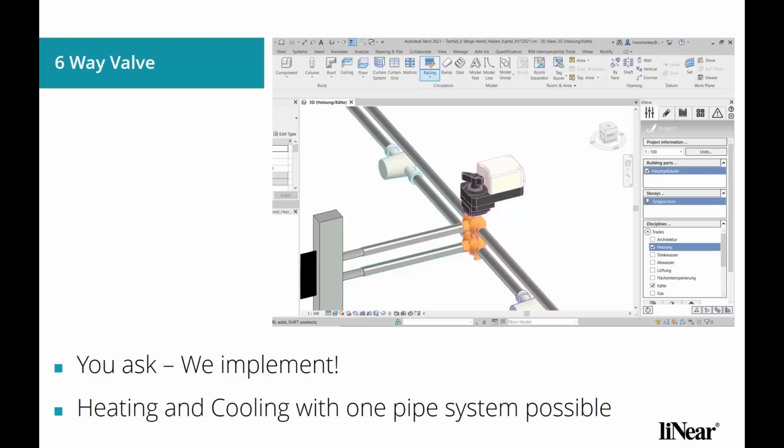With the liNear Analyze modules, this component can also be calculated within the pipe network calculation. With these valves, you can build your system exactly as in reality with cooling and heating modules. For this purpose, neutral and also manufacturer-specific Six-way valves are available in the liNear product library. The desired valve data can be assigned to the components with the valve preselection dialog. You can choose between valves with and without a flow control, so that sections downstream of the Six-way valve can be detected and calculated by both disciplines.